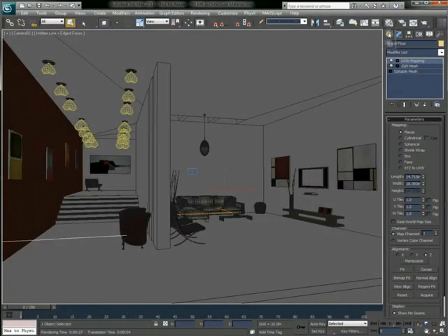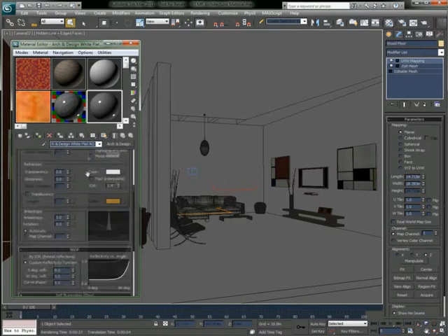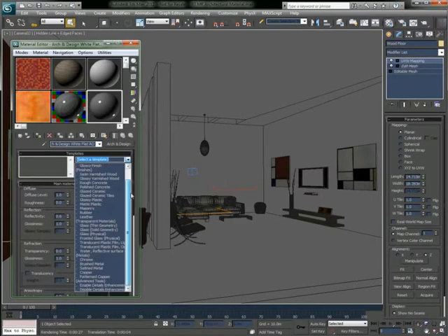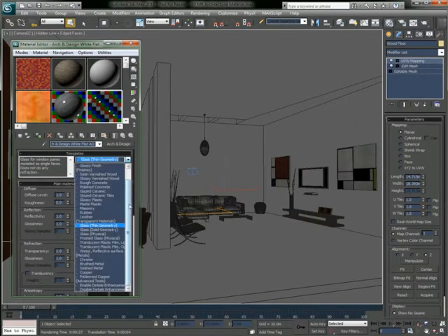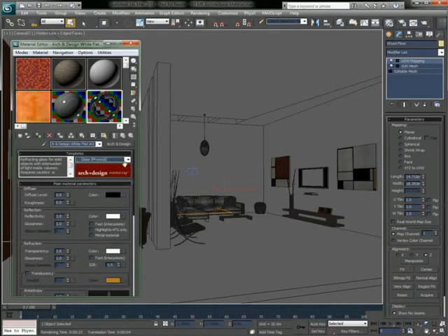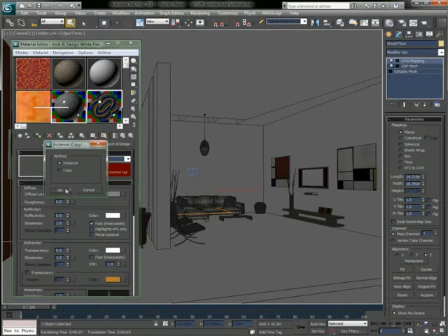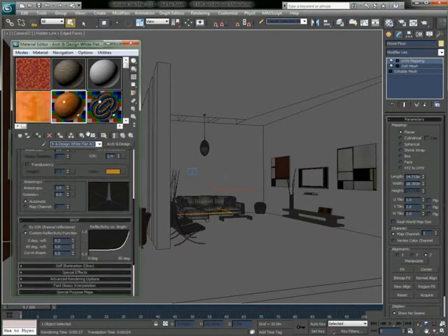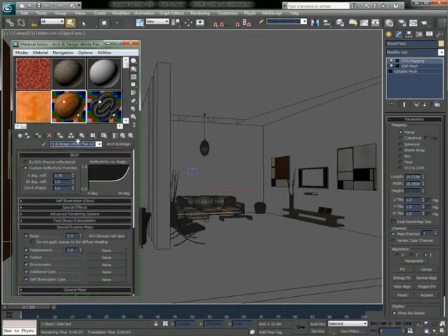The Mental Ray Arch and Design shader is an excellent catch-all starting point for the creation of real-world, physically based materials. Users can start off using the template-based dropdown or, for more granular control, can create more complex map combinations from scratch. The Arch and Design shader has advanced options for local control over things such as reflective falloff, localized ambient occlusion, round corners that require no additional polygons at render time, and material self-illumination based on real-world photometric lighting values.